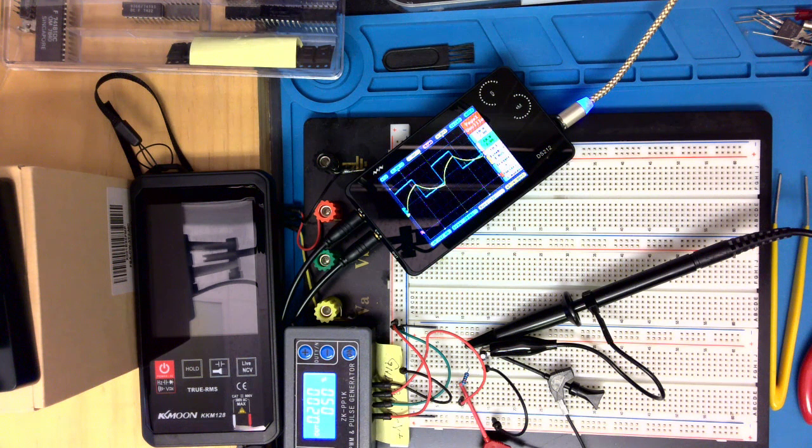And what is so important? This is like a typical timer IC chip. Use a timer IC chip like a 555. It measures how much voltage is accumulated in the capacitor, and it goes to a comparator, and when it reaches the reference voltage, then it discharges the capacitor and starts over again. So that's the way you can control the time of oscillation. So you can create any kind of oscillation time by just the reference voltage and the comparator.